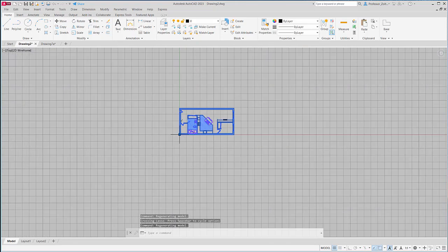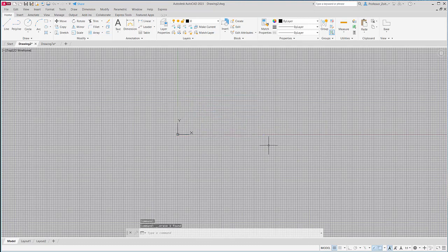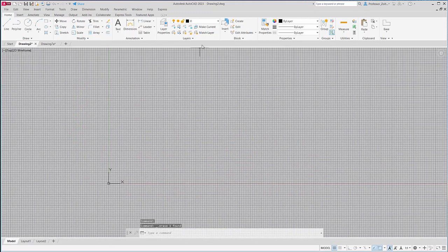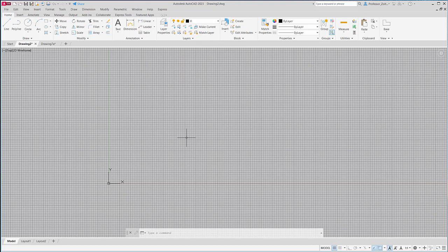So viewport layer or the title block layer, they weren't actually picked in this particular case, and that's why they're not here. Now you can see it's fairly large, but the reason we want to import or paste this block is so I can click on any one part of it and it picks it all. Now I press delete. And so all I've done is save myself some time in recreating all the different layers that we've been working in the past.